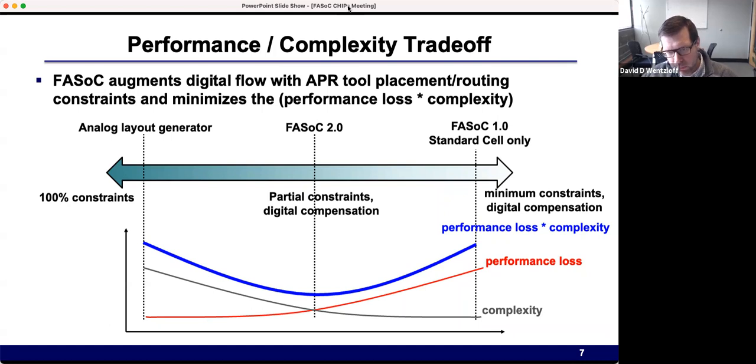For the cells that have not been placed by the script, we can use things like attractors to pull those together. You can usually tell these APR tools to put all the cells next to a pin, because these cells are critical, or this net is critical. So anything touching this net, put them as close as you can.